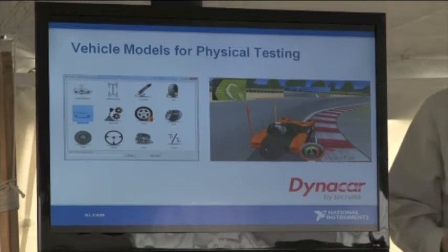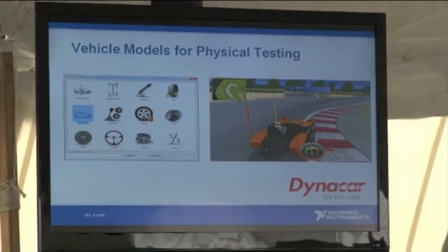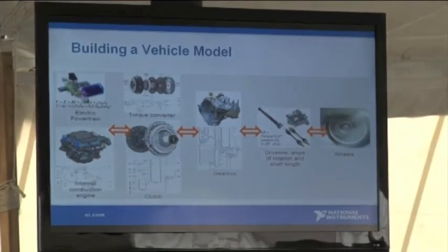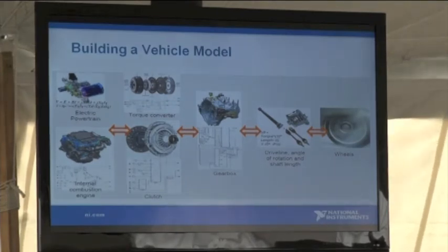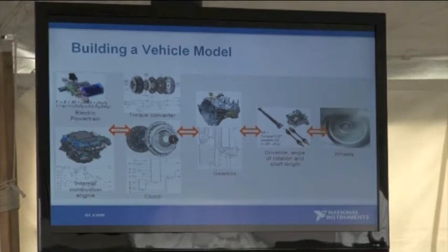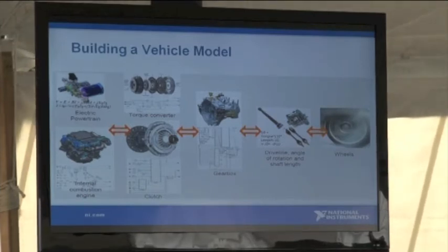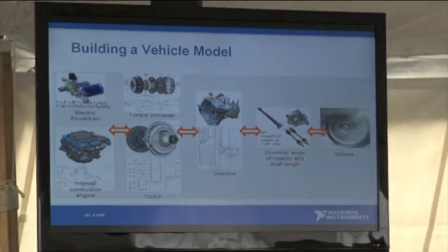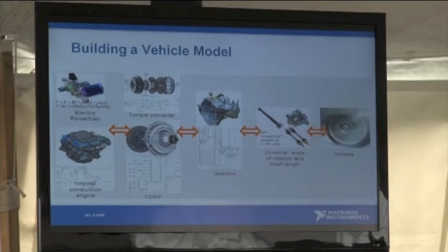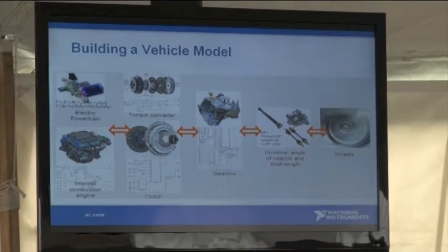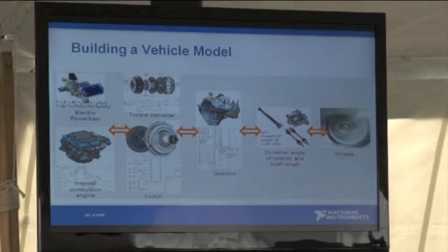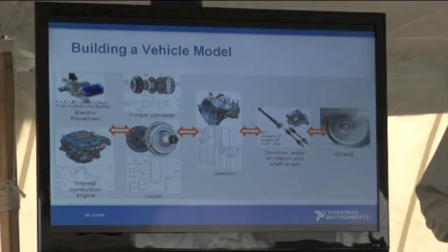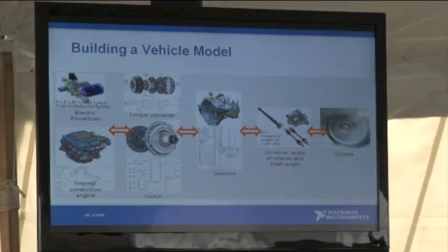And building a plant model is not a small investment because typically, building a plant model, you take into account all of the systems, the physics, the electrical, the sum of all currents, the sum of all torques, and you put these equations together and you parameterize them, and then you take measurements and you get your parameters and you plug those into the equations, and eventually you get an accurate model, but you need to verify that model and continually maintain that model. Now, this is just what the cost is for models, and the return is certainly justified in many cases, especially in the embedded software case. But it's not always justifiable in the test cell or the physical testing world.